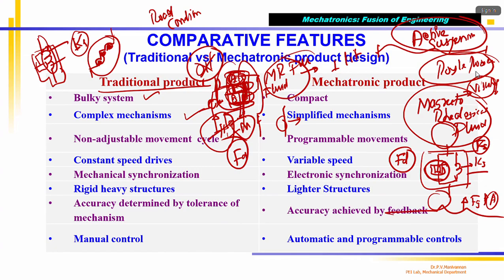So the active suspension system is a mechatronic system in which the current going to the coil is controlled, the magnetic flux is controlled. So finally the damping constant of the MR damper, we call it MR damper. Generally they fix the stiffness constant. They don't vary it. If you want, you can vary it, but it is much easier electronically controlled. Correct. They call it active suspension.